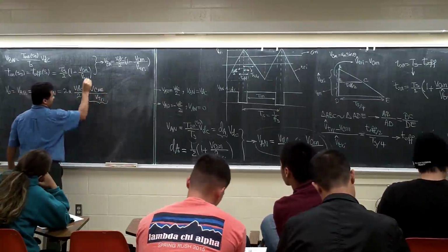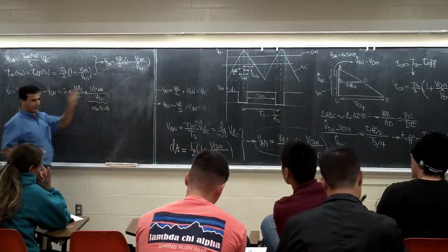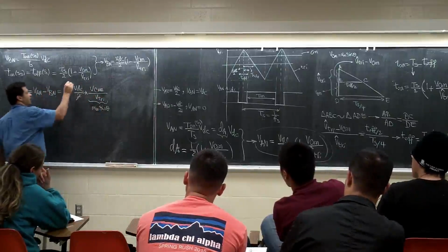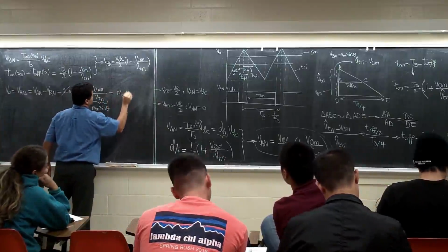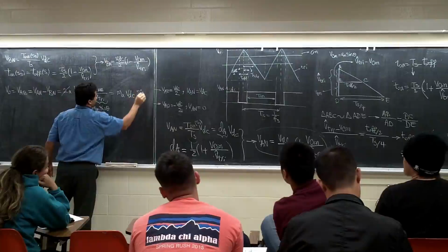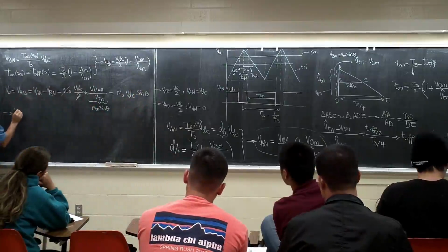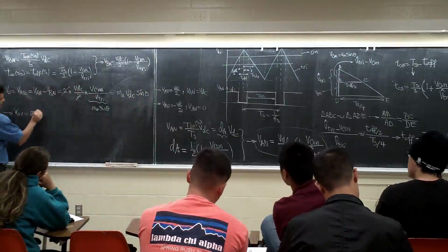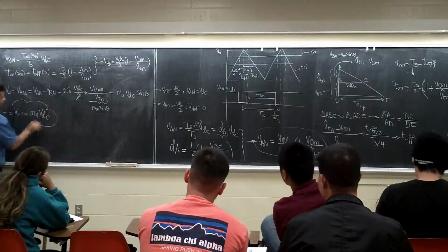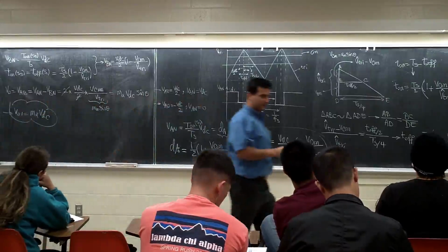And we said, what is this term? It's going to be MA sine theta, right? This term was the MA sine theta. This 2 is going to cancel this one. It's going to be MA VDC sine theta. Basically, VO first harmonic is going to be MA VDC. What's the difference between this one and that one? Half bridge and full bridge?